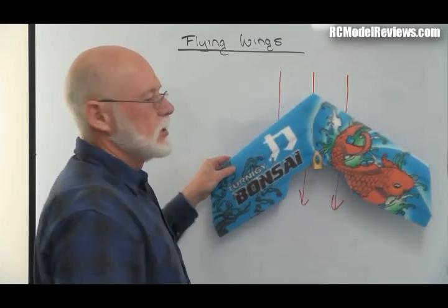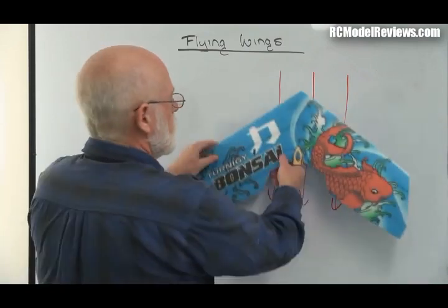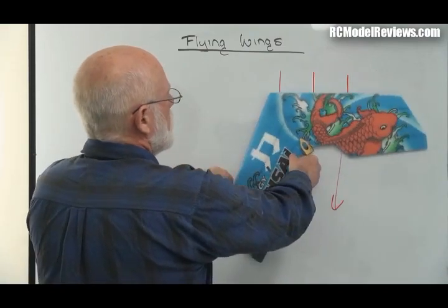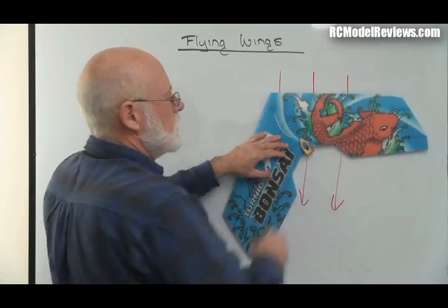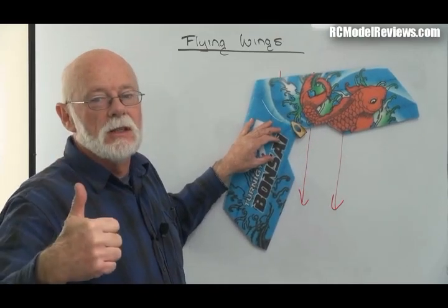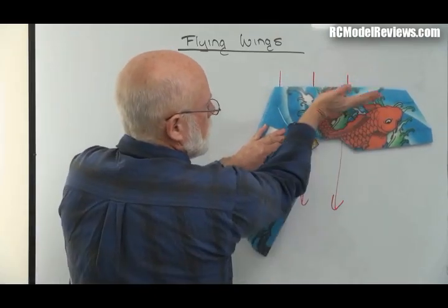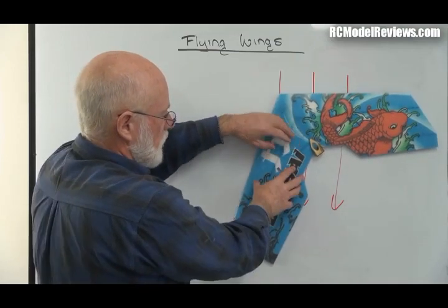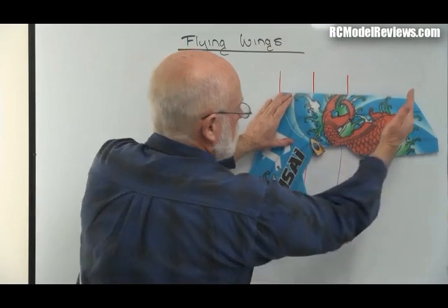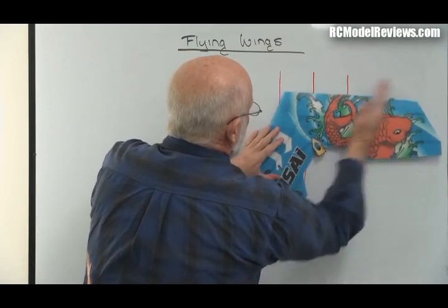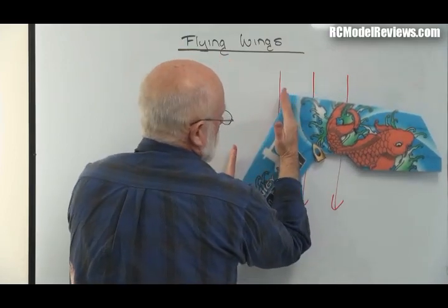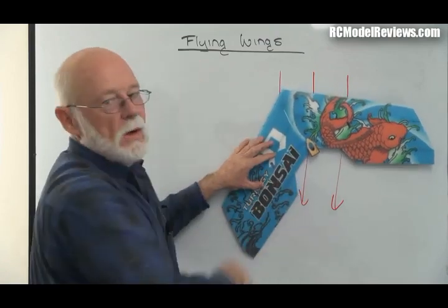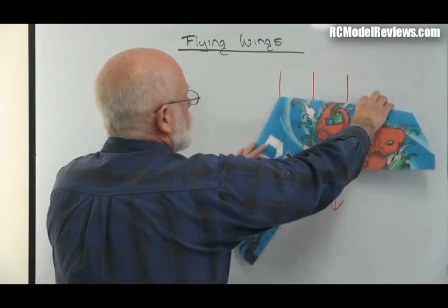But the other thing, which is actually not so good, is that if we're flying along like this and we yaw that way, then suddenly this wing's not only producing more drag, but more lift. Because this aerofoil is straight onto the airflow. This one is sort of trailing out sideways. There's less effective area. If you're looking along here, that's how much wing you see there. On this side, you only see that much wing. So this appears to be a shorter wing once it yaws, which means that it will actually try and roll.